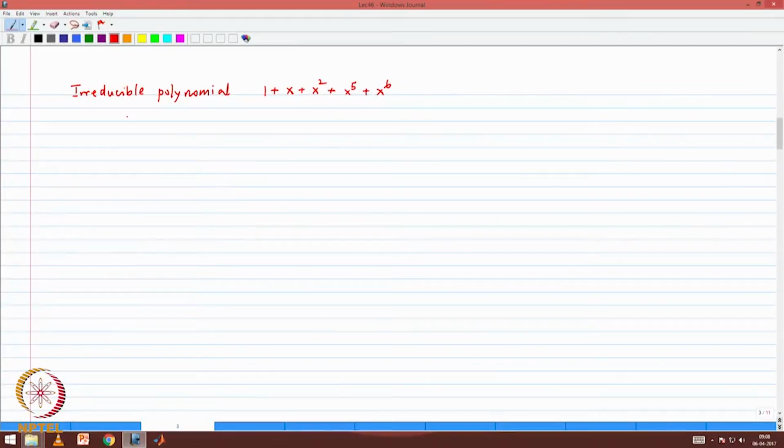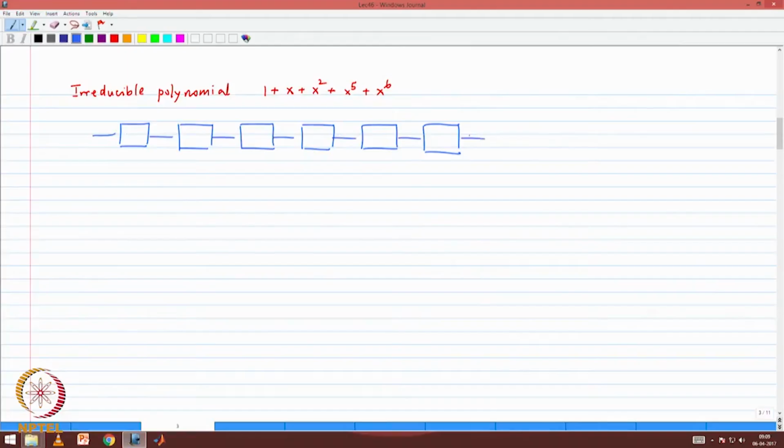You should be able to connect the feedback taps and actually generate one period of the sequence. So this is a 6th order polynomial. So if I want to implement it, I must have 6 shift registers. I can rewrite the polynomial in terms of delays, and please make sure the connections are done correctly, otherwise it may not be a maximal length sequence.